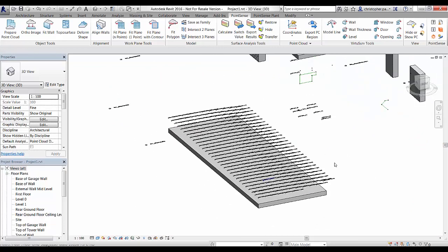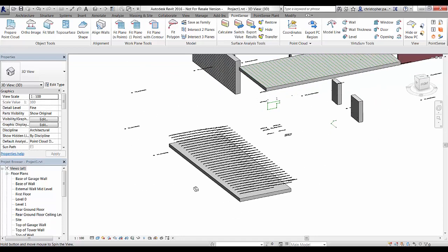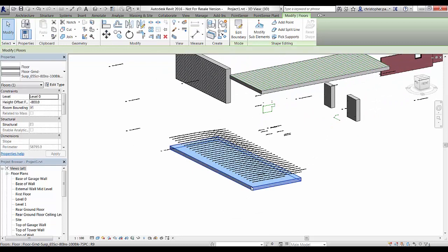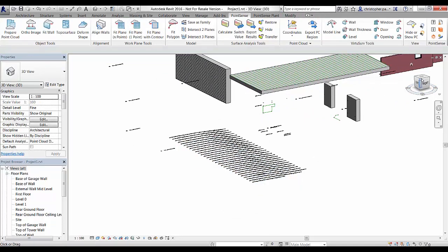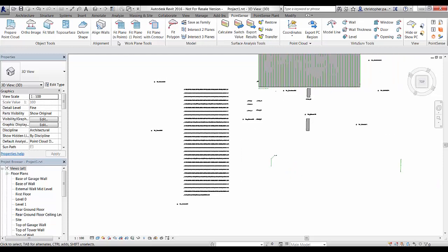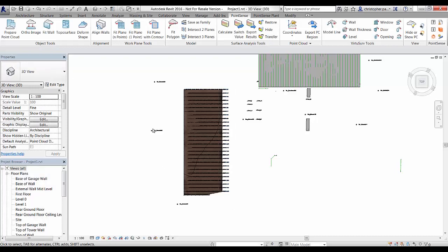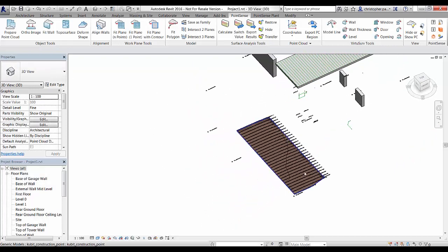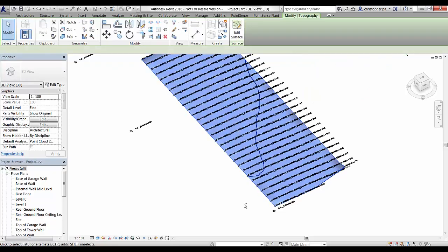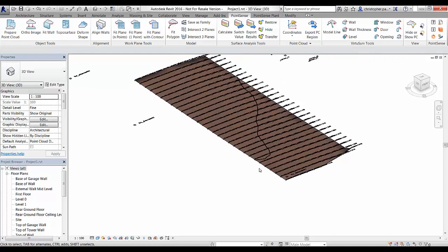Okay, so let's try this similar process down here with the road. First of all, again, I'm going to go in and delete this floor off, and we're going to navigate to the top view. Again, I'm going to go to topo surface, highlight all of these construction points, and then click finish. If we zoom in there now, you can see that's created a nice topo surface for us with the incline of the road and a slight gradient.